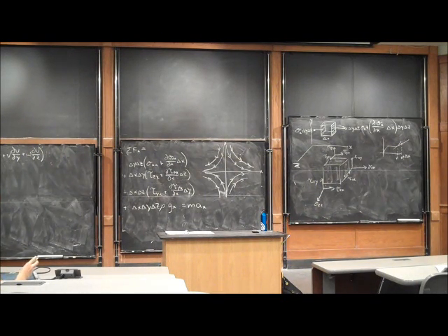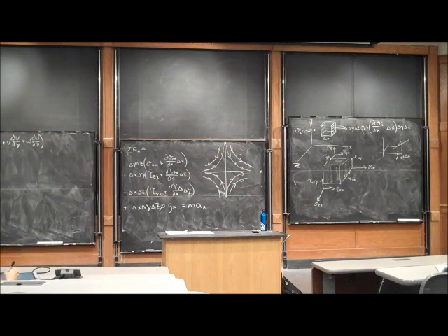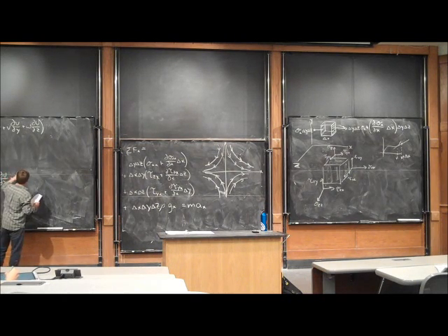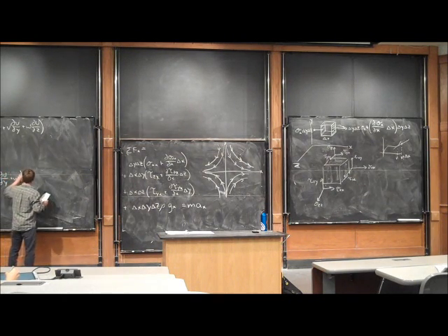On this side, the differential volume just gets divided off, and I have no components of that volume left. So this side becomes rho times del u del t plus u del u del x plus v del u del y plus w del u del z.